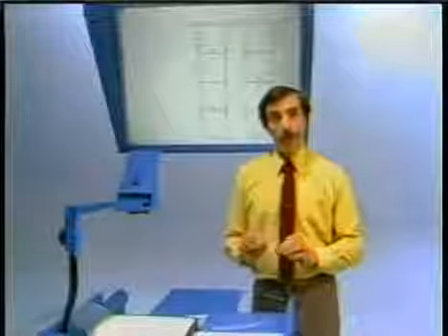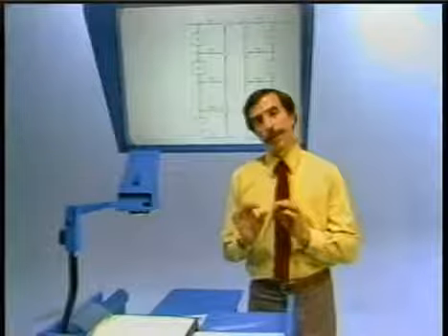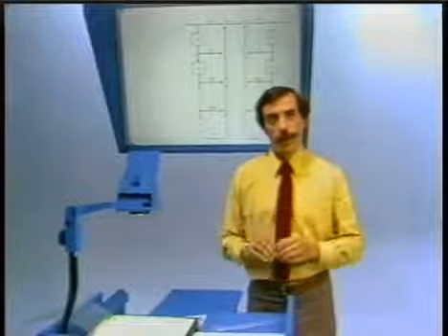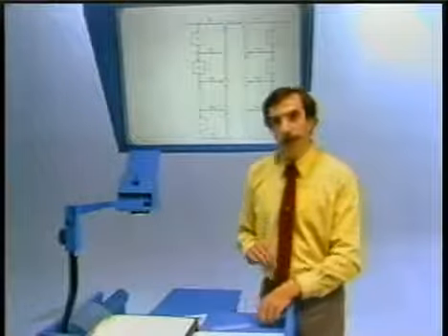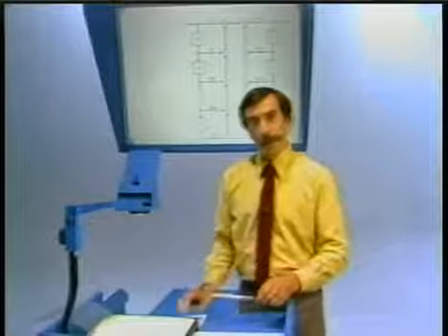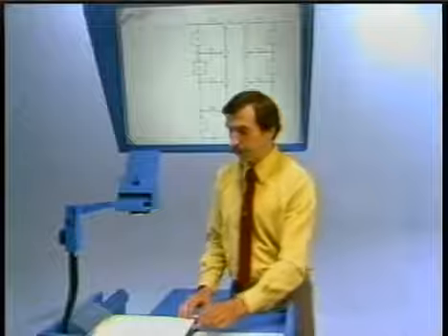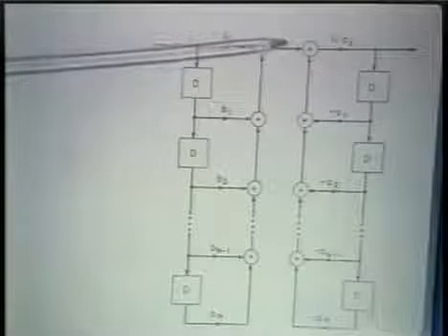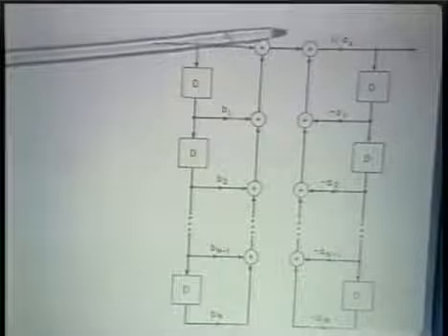Now, that assumes, of course, that my initial conditions are such that the system is in fact linear, and that in turn requires that we're assuming initial rest, namely before the input does anything other than 0, there are just 0 values stored in the registers. But assuming that it corresponds to a linear time invariant system, this is a cascade of 2 linear time invariant systems. We know that 2 linear time invariant systems can be cascaded in either order.